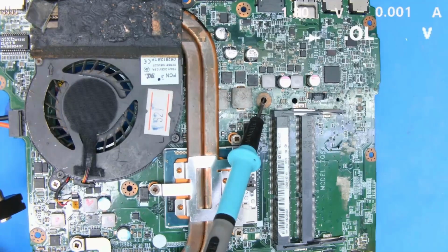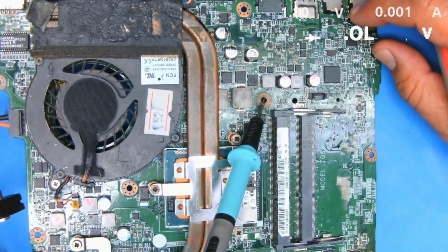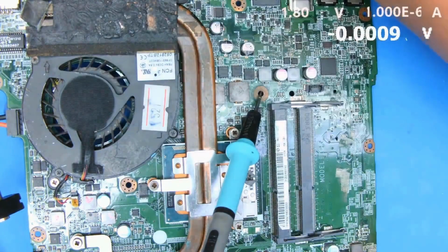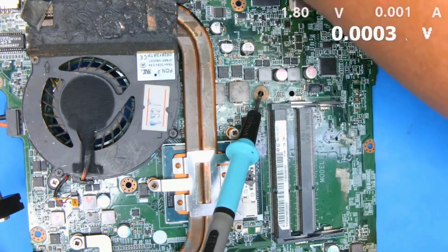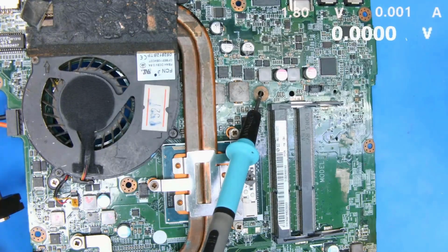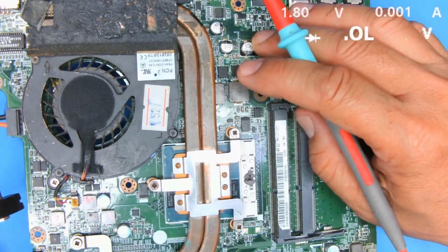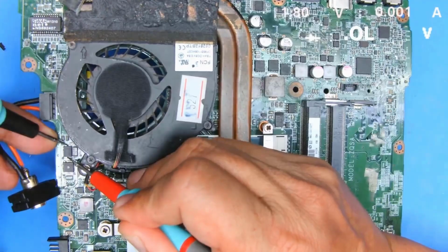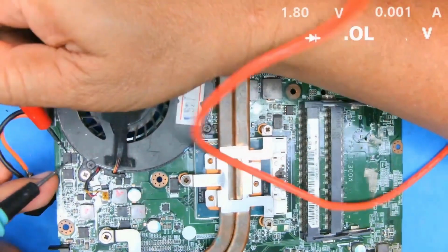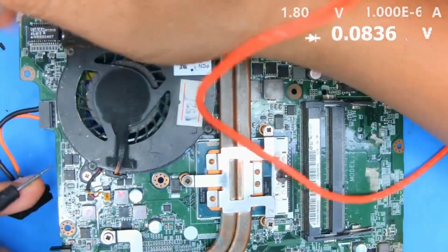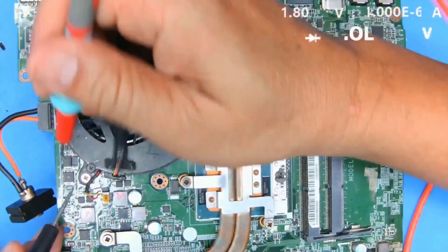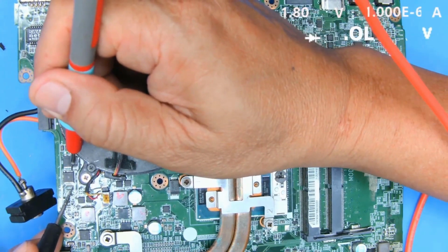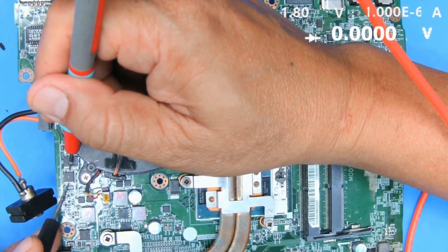At this point, if you want to measure voltage, you can go ahead and supply power. You can try powering it up, but most importantly, don't forget to check the power rail thoroughly first to make sure it's not shorted. Try measuring the middle pin on that side and the middle pin on this side. Always measure in diode mode every time after you recheck. Then check the power rail set that's close to the adapter. In this area, there will be a diode. Just measure across it. This one shows OL, which is the diode value on this side. The diode value on this side is okay. Normally, for this power rail point, you measure between the side with the round marking and the opposite side like this. See? It reads 0.00 on the display.